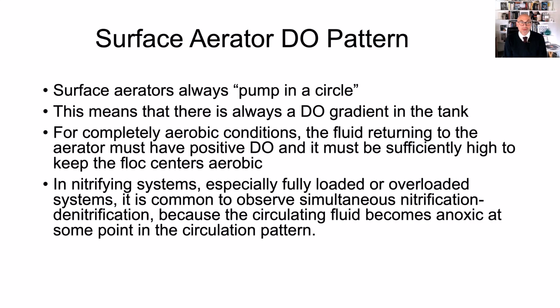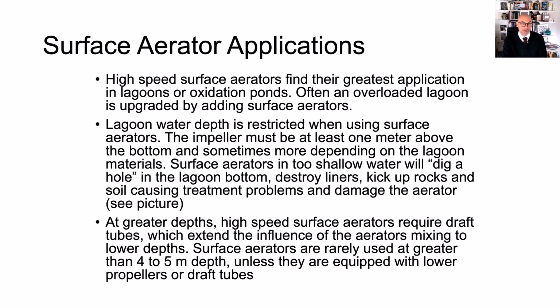You might have some issues if you do not have the DO, the dissolved oxygen, to be sufficient at some point. So that's something to be kept in mind. If you have lagoons, oxidation ponds, these were the typical applications for surface aerators in the past, but a lot of those have been decommissioned or converted into diffuse aeration systems.